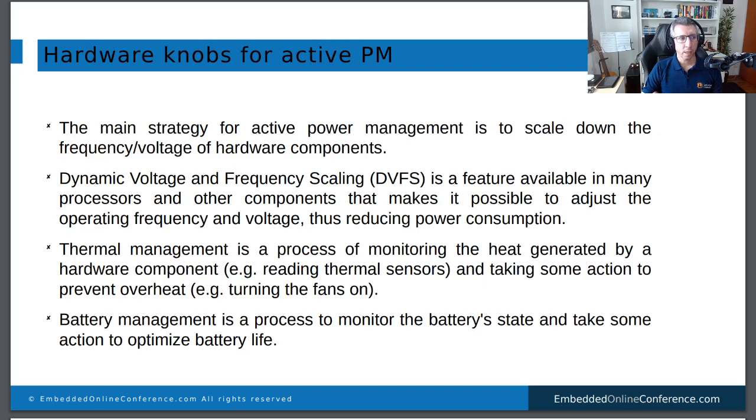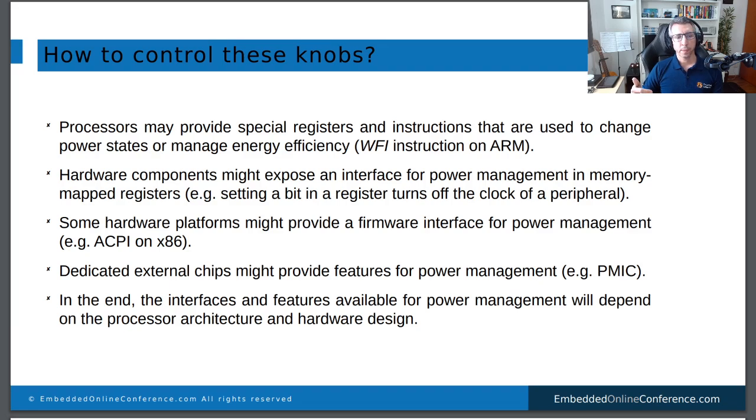So there are several techniques that you can apply. At the hardware level, you need support for this, and most modern hardware provides support for it. For example, on ARM, there is an instruction, WFI, that you can use to get a CPU into low power mode, into a low power state.